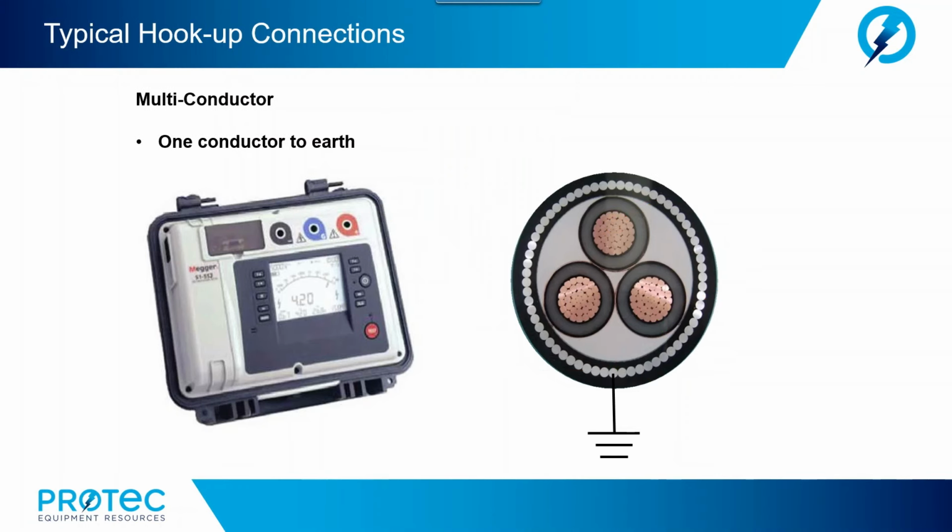Now, we may wish to do some isolation, where we only want to measure one conductor to earth without the influence of the leakage current flowing to the other conductors. So to do this, we would once again short out the two conductors that are not involved in the test.